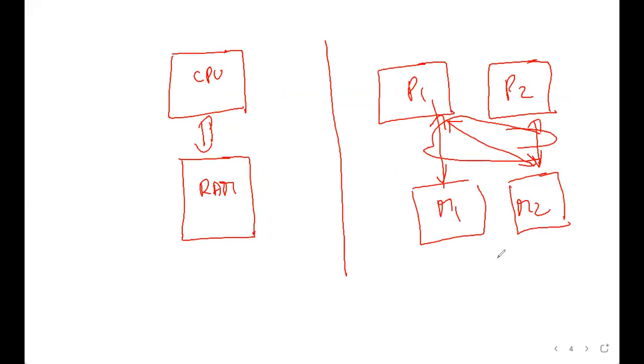But instead of this being the final memory, in the cache hierarchy itself, you will have an L2 shared cache, which is distributed amongst all the cores. So the latency will depend on whether the L2 cache is exclusive to core 1 or shared between core 1 and core 2, and how you're pinning the regions in the L2 cache. Because otherwise you'll have cache thrashing, where core 2 is replacing a particular cache row, and then core 1 accesses that again, and it's a miss, and so on and so forth.